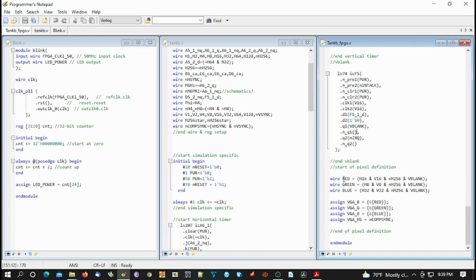Then we take those reds, which are one single bit, and we need to make them a 6-bit wide entity for the VGA, because we've got a good color depth on MiSTer, which means you can get lots of different colors. That color depth is 6 bits wide. To create it, we concatenate that one red bit 6 times, and that's what these curly brackets do.